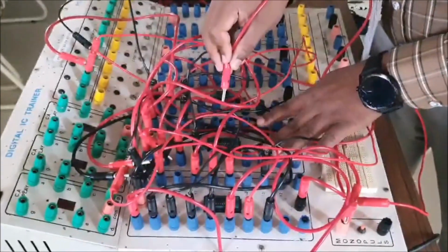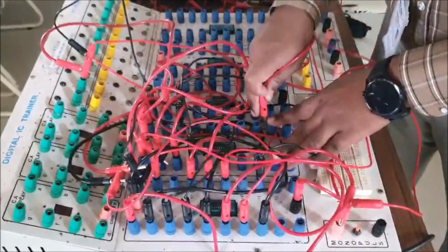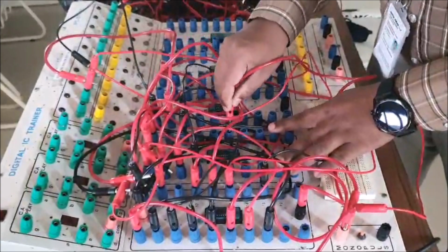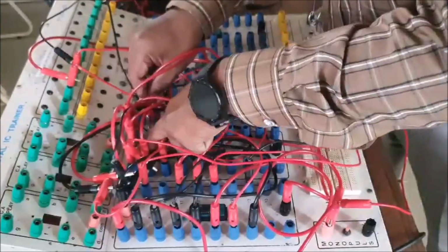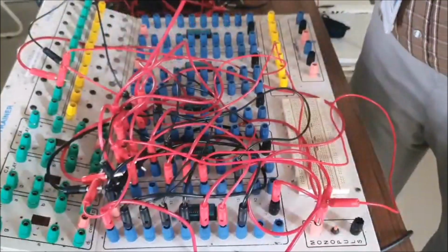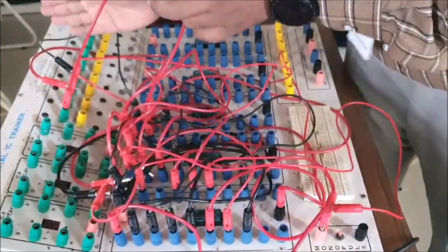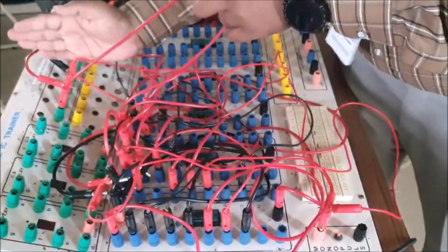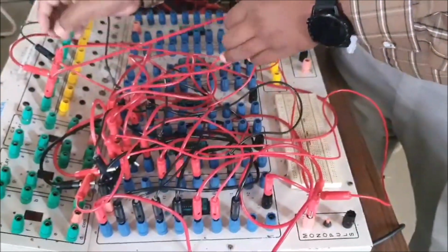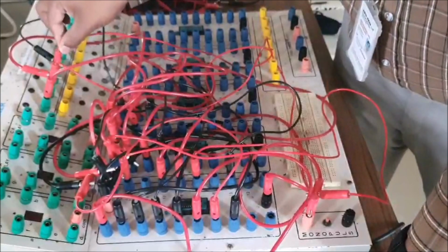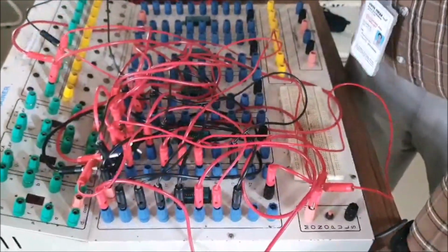In the second IC base, on the left hand side we have 8 pins. Coming to the bottom right, this is 9, 10, 11, 12, 13, 14 and 15. I will connect one end of the patch cord to the 15th pin. Another end is connected to QC, which is nothing but the third output. Here I am reading the output from right to left, not from left to right. So from the right it is QA, next is QB and the third output is QC.